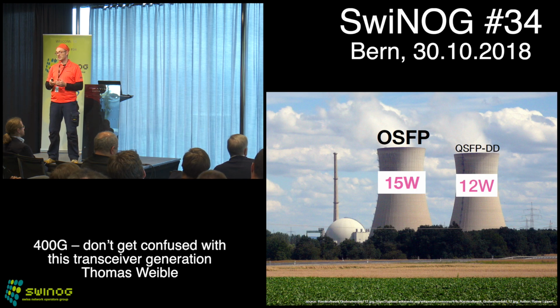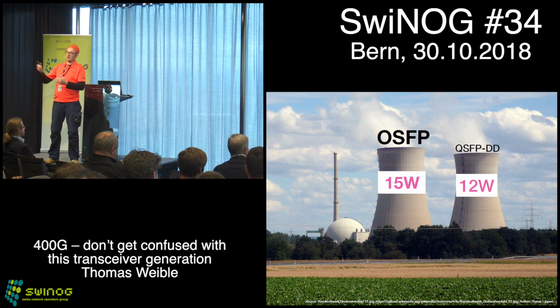The goal for 400 gigabit is getting DWDM technology into a transceiver, coherent DWDM, running up to 80 kilometers. To do that, you need a DSP, a signal processor, which is able to process the coherent signal, and this one needs power as well. This is one big target for the 400 gigabit, not only taking into consideration the small data center or the short distance data center interconnects for 500 meters or up to 10 kilometers, but also in a later step, I would call it generation 3, going up to 80 kilometers doing coherent DWDM.